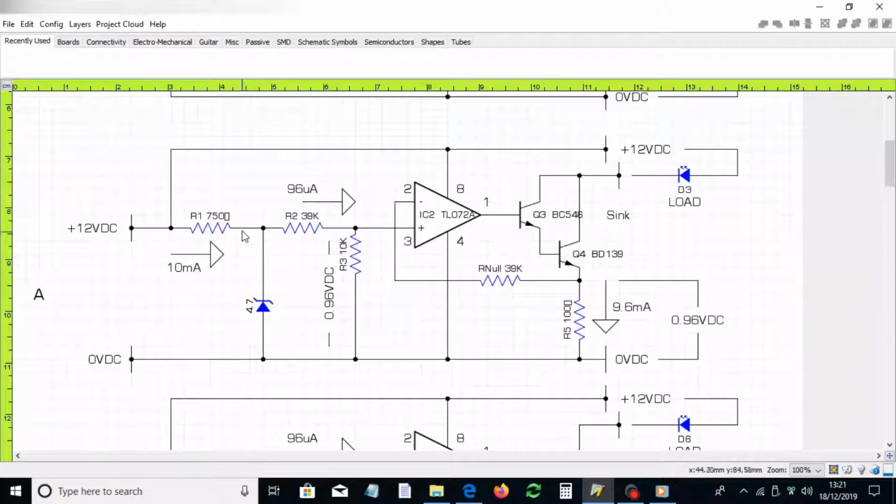You can also include here a constant current source, so that you only have a fixed current going through the Zener diode, and thereby stabilizing its reference. You can also put a Zener diode within a small oven, and the oven will keep a fixed temperature, thereby establishing a fixed voltage here.